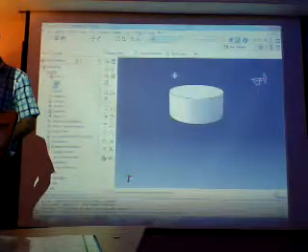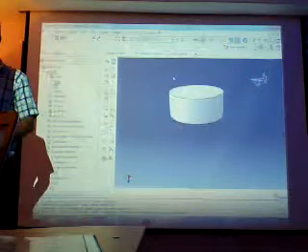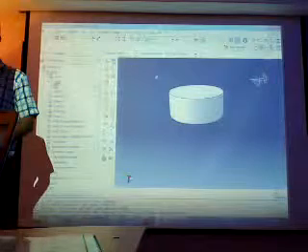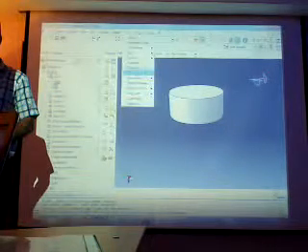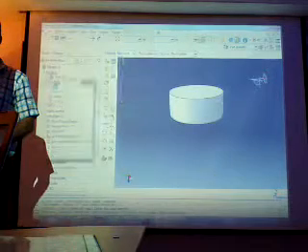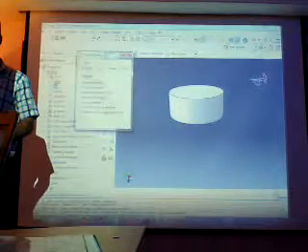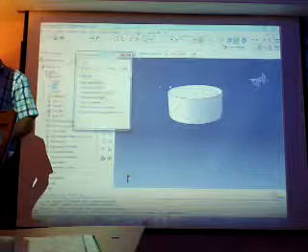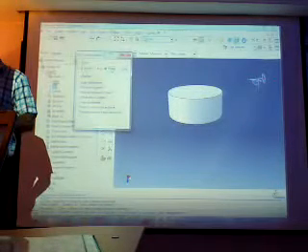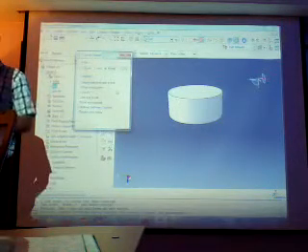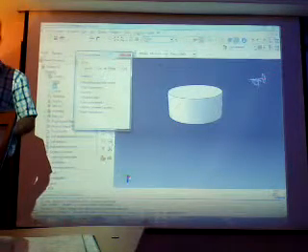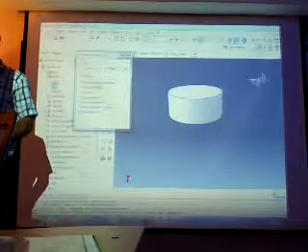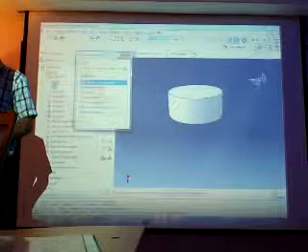For simplicity in assembly, we also need to define a datum plane for this part. Here you can define datum for your part. It's possible without a datum plane, but by taking the axial plane, your assembly and your interactions will be much easier. Offset from principal plane.